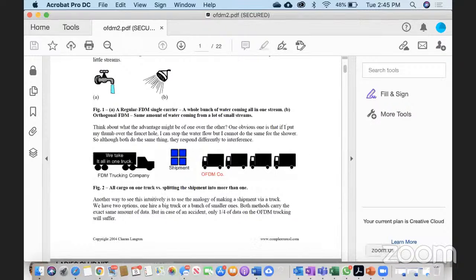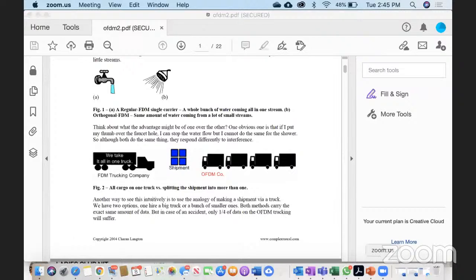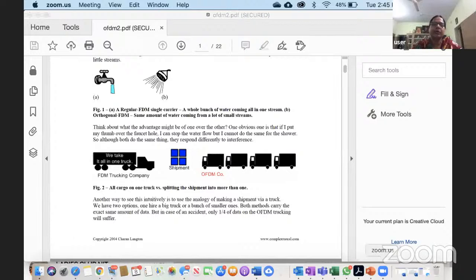Which constellation mapping is better, QPSK or QAM? The basic modulation schemes. If you have studied the different modulation techniques available in digital communication, as I said, from BPSK to QPSK, and from QPSK to QAM, what is the advantage we are gaining from one modulation to the other? In BPSK, the points are separated by distance, one on the right side and another on the left-hand side. And we have also derived the probability of error equations.